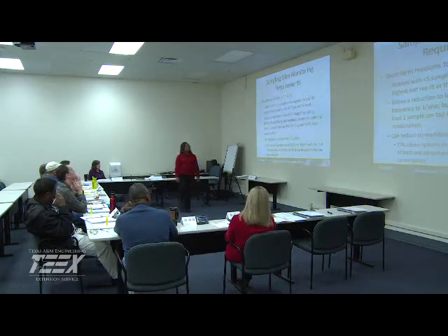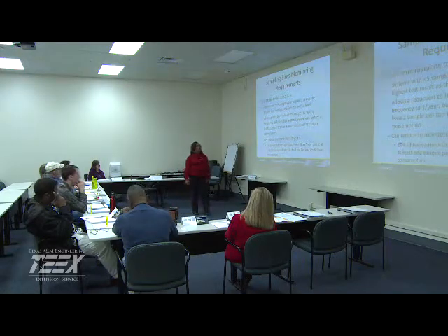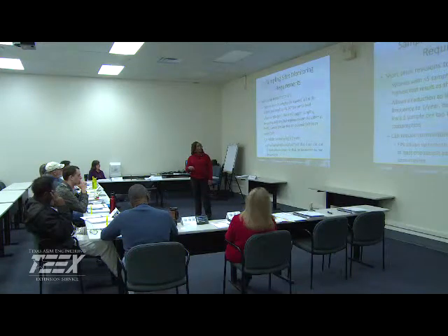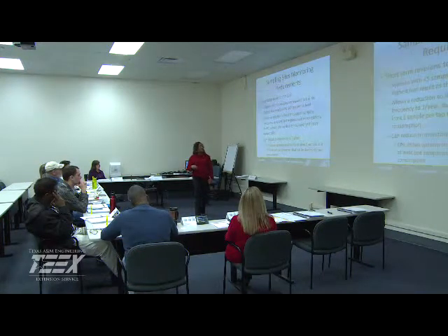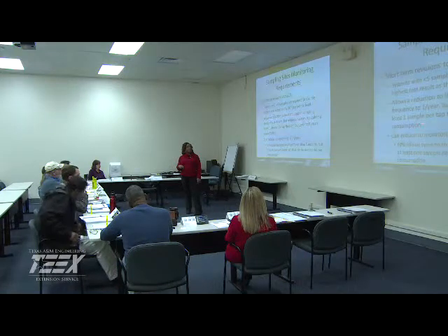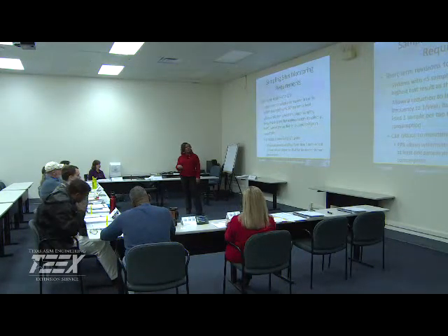All right, other short-term revisions: systems with fewer than 5 samples are required to use the highest test result as the 90th percentile level. It also allows for reduction of lead and copper sampling frequency to once per year, but it requires that the system collect at least 1 sample per tap that can be used for human consumption.